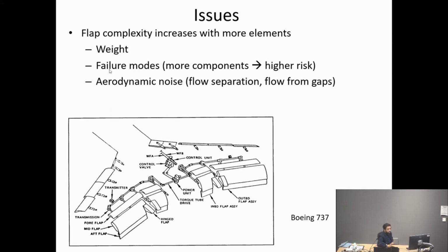Now, has anyone done systems engineering? In general, you might think, if I make something more complicated and it works fine, I'm fine. The problem is, the probability of things going wrong goes up with the number of components you have, right? Because you're connecting things together more, that will actually reduce your reliability if you're not very careful. So you have to think about failure modes.